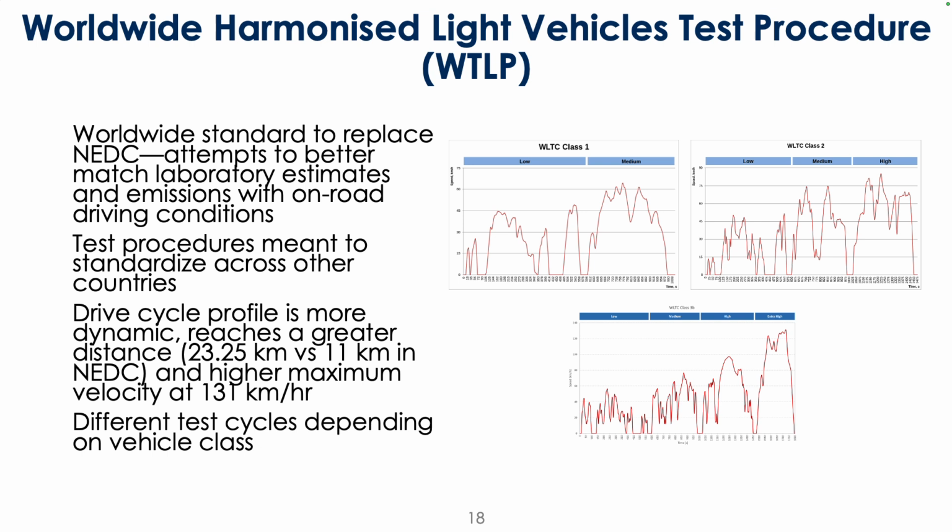So WLTP, I would say, still overestimates your fuel efficiency, but not nearly to the same extent that NEDC was. The other thing about WLTP is that it's harmonized across the world, and so the test procedures depart a little bit more from the original NEDC, which was meant to emulate a lot of the city driving.